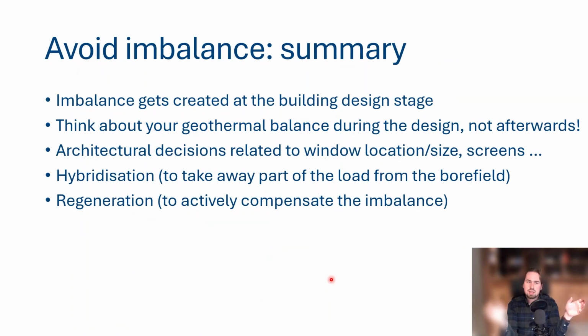So let's summarize. How can we avoid the imbalance? Now, the imbalance is something which gets created during the building's design stage. And it's better to think about your geothermal balance during the design of your building, both architectural, but also from a system point of view, and not afterwards. Because then you have to cope with the imbalance and you have to change quite a lot about your geothermal design in order to cope with the imbalance. And that we discussed last time.